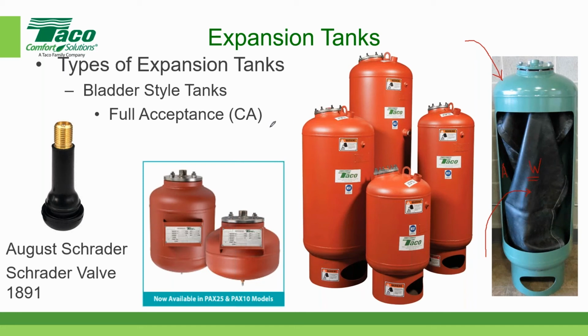So a full acceptance bladder style tank has a bladder, it has a void space where the compressed air goes, and it has the steel container. And it gets its name full acceptance because the bladder can hold the same physical volume as the steel container. So in our simple example, if the steel container is 200 gallons, then the bladder will also hold 200 gallons.